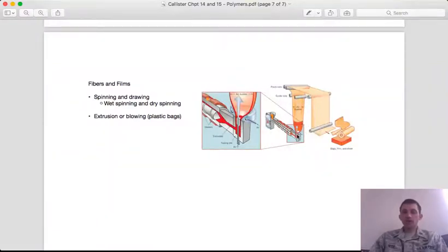So as you are extruding it, you're essentially blowing like a big polymer bubble, and that air acts to expand and cool the film, and so quickly you can collapse the bubble without it sticking to itself, and then roll that up, and it just seems a very elegant way of creating those plastic films. This reminds me of watching like how it's made, and like the industrial process of doing all of this.